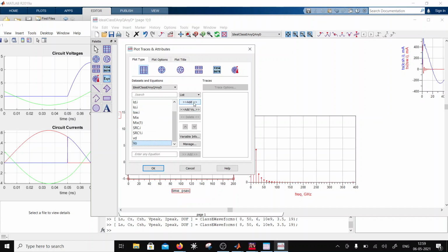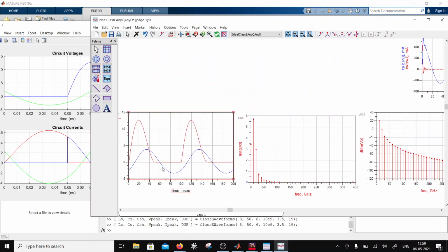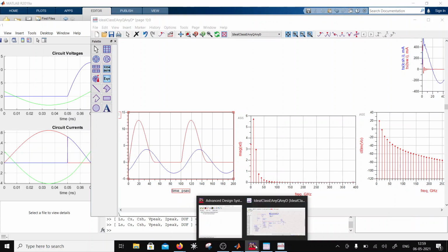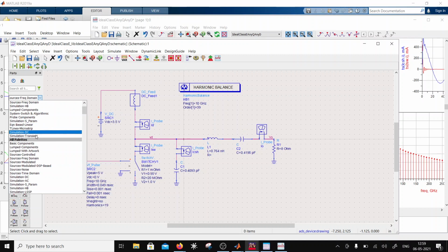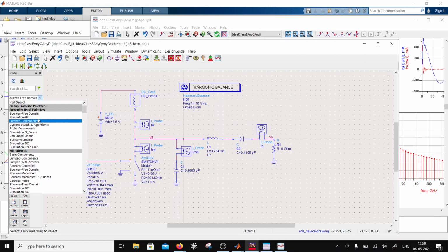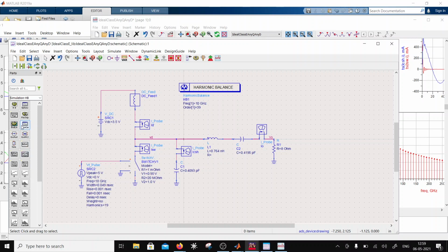So I can do a VO and say spectrum in dBm, and I'm putting out here 21. So let's look at the supply voltage here. Supply voltage is 3.5. So why am I putting out 21? Okay, this is an 8 ohm system, so this is computing in a wrong way. So the way to compute this would be, I write a measurement equation. I will go to harmonic balance measurement equations, because this is not a 50 ohm system, so that formula for dBm is wrong.